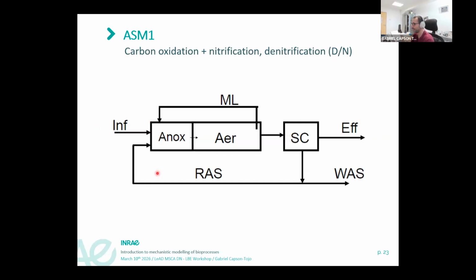Well, basically what's happening here is that we have influent wastewater going through an anoxic and an anaerobic tank. So this is where the biological reaction happens. We have certain recirculations and part of the biomass is sent back, so we can actually perform the reaction effectively since the beginning due to biomass recirculation. I hope most of you are aware that this process exists. But in our case, what we care about, again, are the reactions. All this recirculation, as I showed you before, is just a matter of mass balancing.